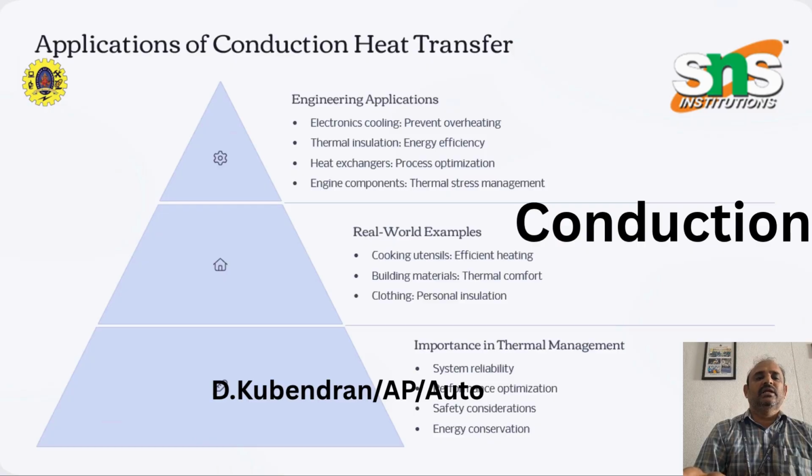Mathematical modeling: heat conduction equations are solved using analytical or numerical methods. The heat equation is a partial differential equation derived from Fourier law. Finite element method and finite difference method are used for numerical analysis. Boundary and initial conditions are essential for solving conduction problems. Solutions help predict temperature distribution over time.